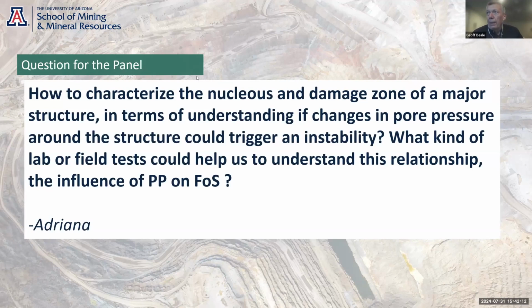And again, I'll post on the website a paper that was done in April, and it again really starts to focus on whether the structures are parallel to the slope or perpendicular to the slope. And we see lots and lots of instability where the structures are parallel to the slope because they dilate, water gets in, and then the pressure of the water can start to form a stress on the slope and lead to instability. You can only develop a relationship between the pore pressures and the factor of safety if the fault was actually moving in the field.